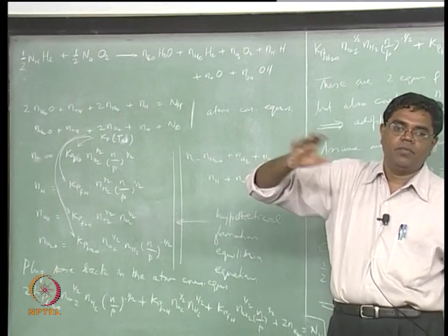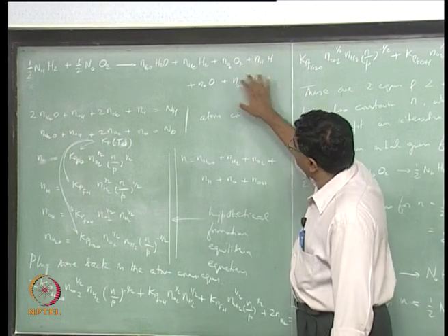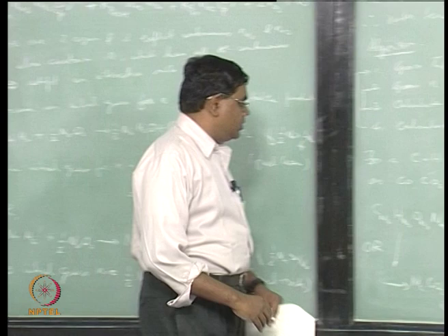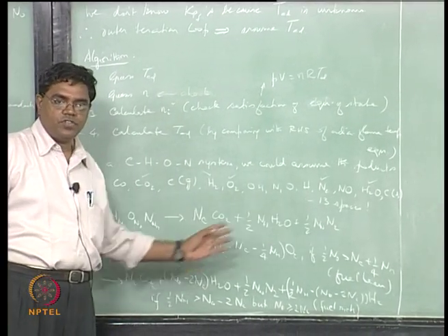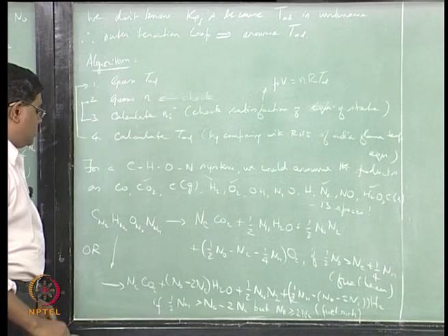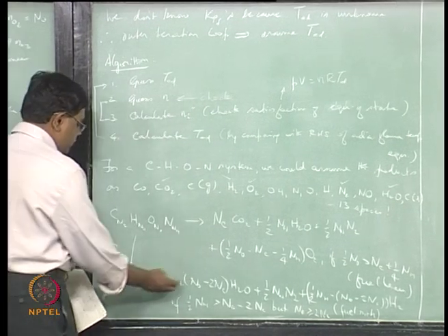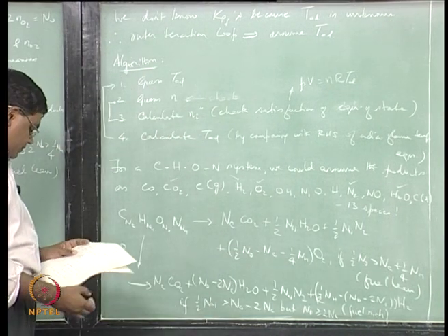So there is an equilibrium that gets attained by having more of these and getting the temperature down. So that's the reason why we are starting with an initial guess based on the stable products composition. If it's a fuel rich situation, you can add up these in order to get your initial guess for the total number of N.